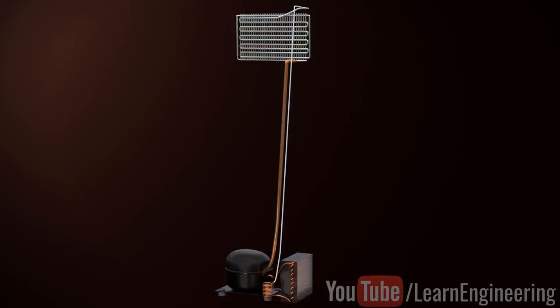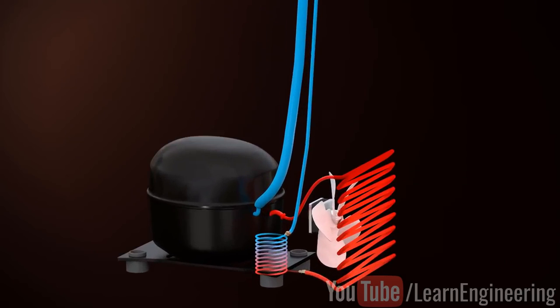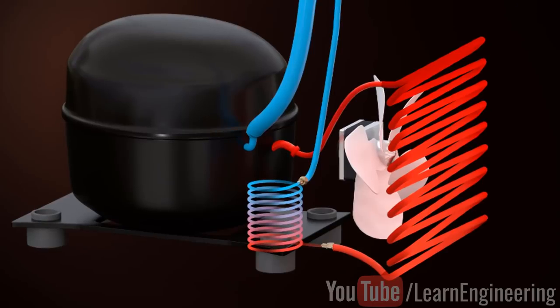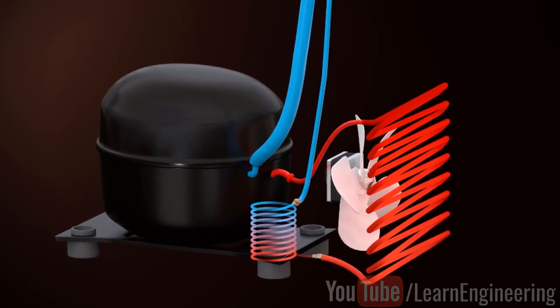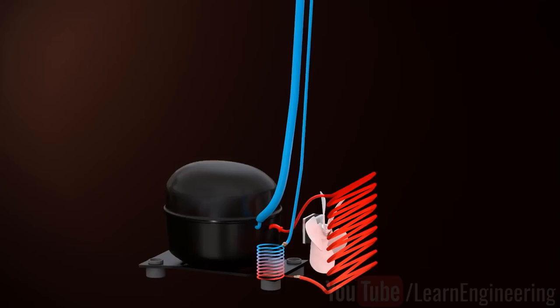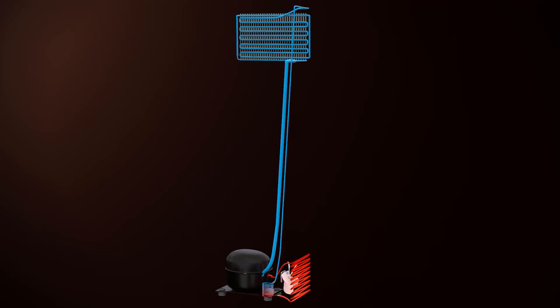An interesting temperature distribution in different parts of the refrigerator is illustrated here. The temperature drop across the capillary tube is also clearly depicted here. You can see two refrigerant lines outside the refrigerator. One takes the cold liquid from the capillary tube to the evaporator coil, and the other, the exit vapor line from the evaporator.